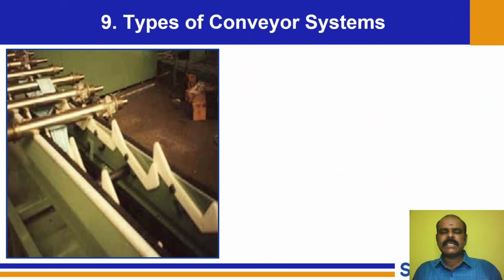So this is what it looks like. Walking beam means on the side you will have two slots. You can see there are two slots, and these are the slots which will take up the workpiece. It's a small fixture-like thing. Based on the workpiece we can have a uniform gap, the pitch. The uniform gap can be ensured between two consecutive tooth-like structures. Between these teeth you can place the component. It can be anything, cylindrical or anything.